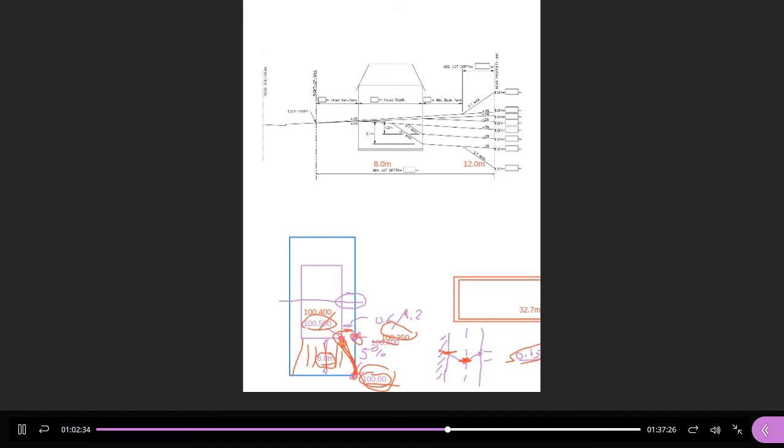If you're between these two numbers, then what I would do is start at the front and go up at 3%, and start at the back and go down 3-to-1. And then I'd have a little extra usable backyard. In fact, any number between 0.98 and 2.56 would have that solution. So let me draw that one more time.